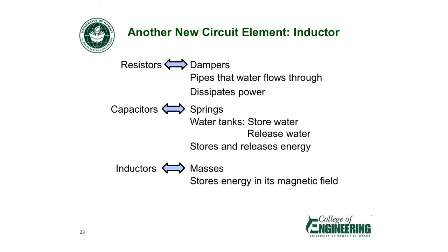Inductors are an element that can store energy as well, but I start to lose the effectiveness of the water analogy because we're storing energy in a magnetic field, and the water is supposed to represent charge. I don't have another representation for the magnetic field. But in the mechanical version of the system, where resistors are dampers, capacitors are springs, inductors are going to be like the masses in a spring damper system.